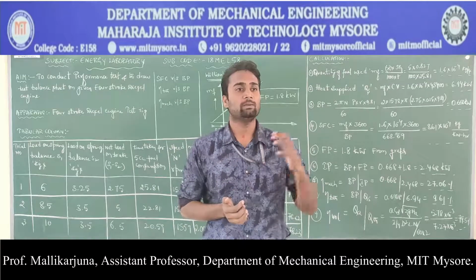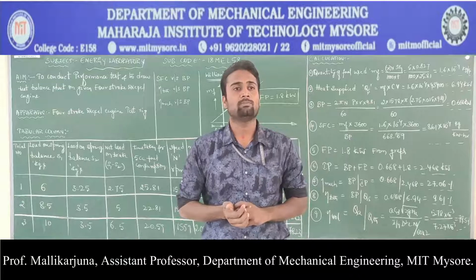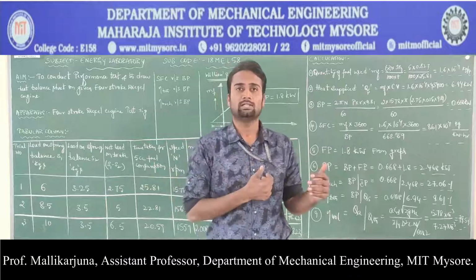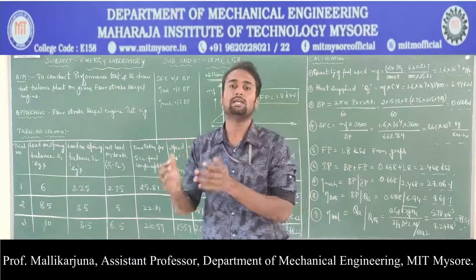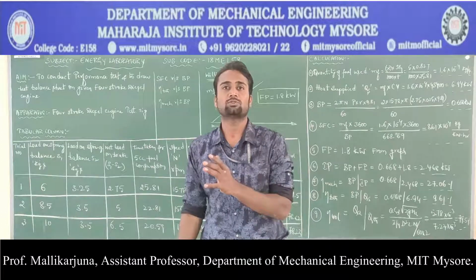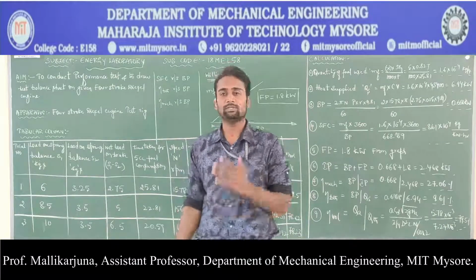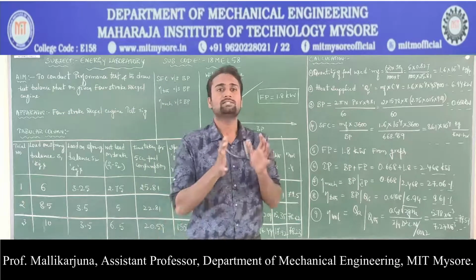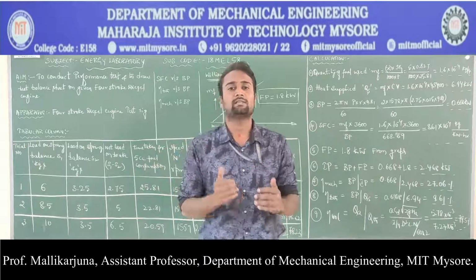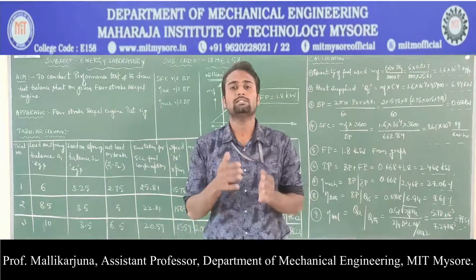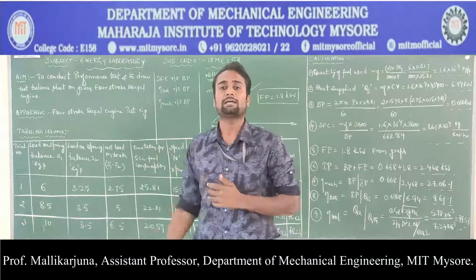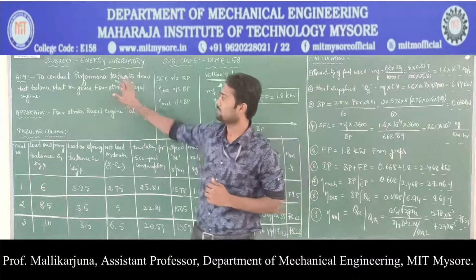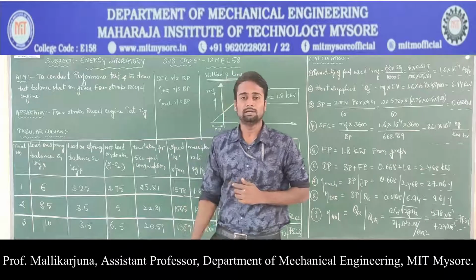What we have to do is conduct the performance test. Performance test in the sense how various factors are dependent on each other, how one variable is going to change the other parameters. Those things need to be analyzed over here. Along with that, we need to plot the heat balance sheet, in the sense how energy distribution is taking place inside the engine, or how the engine is utilizing the energy for various aspects. That needs to be drawn in the form of a heat balance sheet. So that is our aim in this experiment.